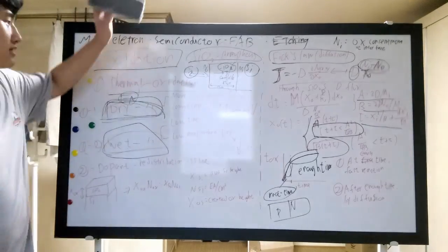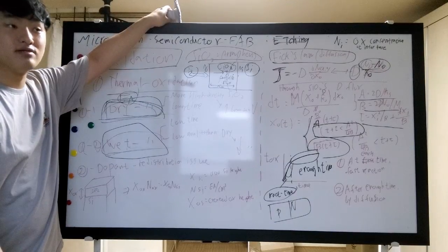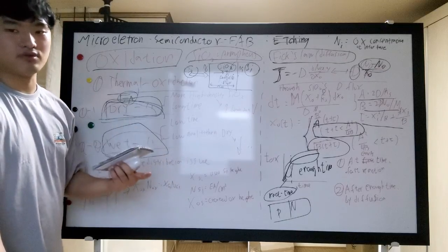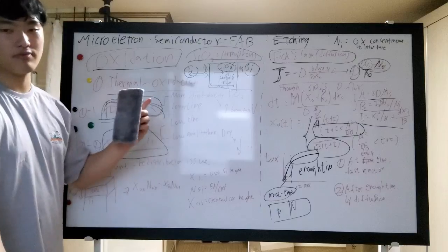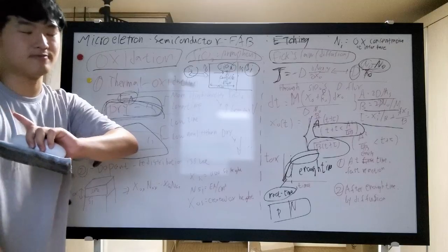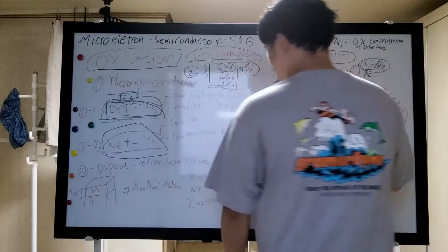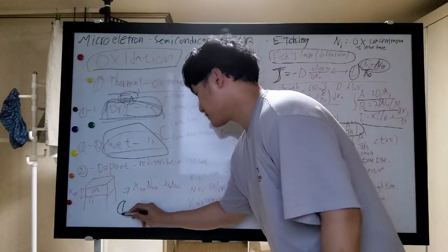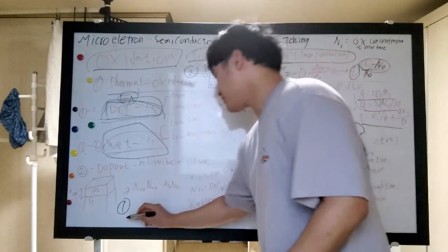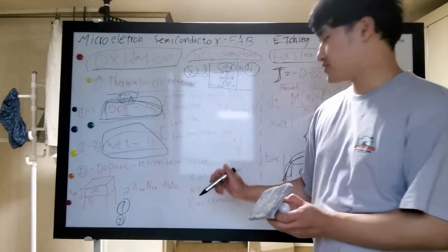So if the silicon that we oxidized was somewhat doped silicon, not pure silicon, P-type or N-type doped silicon, here is a problem. Then where will the dopant go, to the dioxide or to the silicon side? There are two types. First, going to the dioxide side, and secondly, moving to or staying in the silicon side.